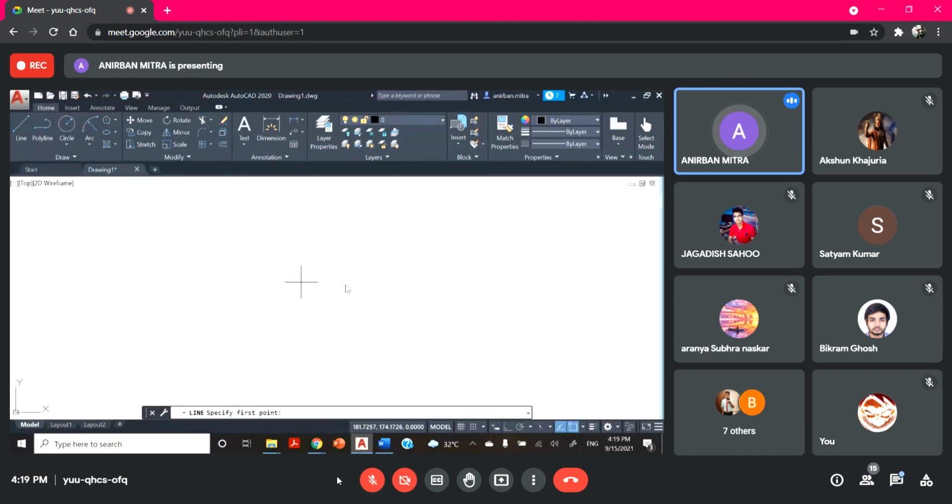I'll select line. I'll start with @40 angle 180, then go down at the rate 35 angle 270 or minus 90. Now at the rate 40 angle 0.